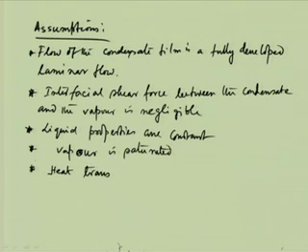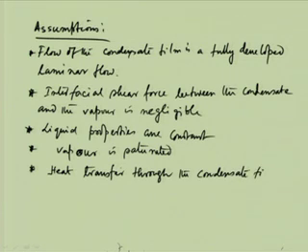Some of these things we have not discussed yet; we will be discussing these assumptions while we try to find out the values of the heat transfer coefficient. So, heat transfer through the condensate film is by conduction mode, and then we have that the temperature profile is linear.